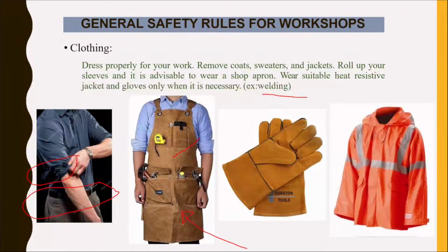This kind of apron you can wear. Wear suitable heat resistive jackets and gloves only when necessary, right? For example, for welding and casting, you have to wear heat resistive clothing to prevent unwanted heat from entering your body.